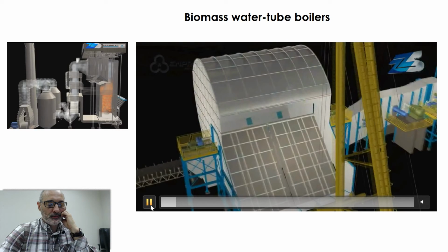Now this is separation of straw. Here you have sand and mineral residues being separated. I'm going to stop at the diffuser. You can have roll mills here or a diffuser, depending on your, I would say, religion. So here you extract juice, and here you have bagasse. Bagasse with 80% humidity. You pass that through 2 roll mills in order to dewater.